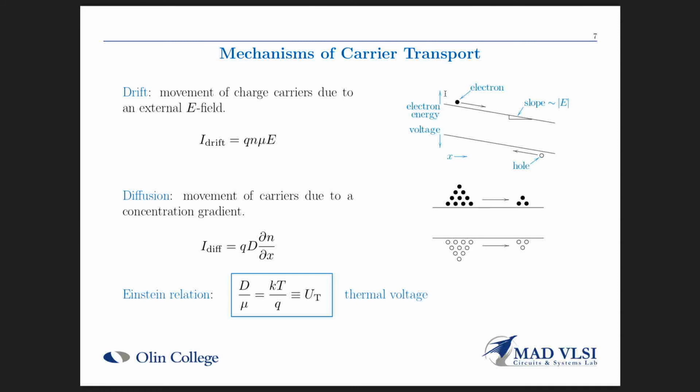And like I said, if an electron is free to move and it has some velocity, it moves up off the conduction band edge to a different higher energy level in that range of energies, or band of energies. And then this range of energies down here is called the valence band, and this is where the electrons that are participating in covalent bonds all live. They all live in this range of energies down here. And it's also where the holes live. So the holes live in the valence band, and the conduction electrons live in the conduction band up here.